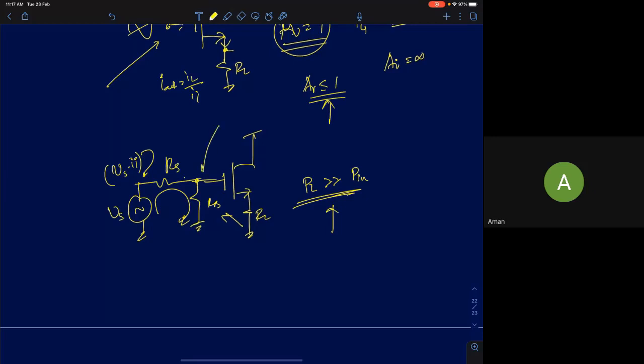For example, yesterday I discussed a problem where you had a bias resistance RB connecting to a DC voltage source VB, which was used to set the DC voltage at this point. Now, for AC analysis, I can assume the DC voltage is a short. So you will still be drawing some input current from the voltage source Vs.